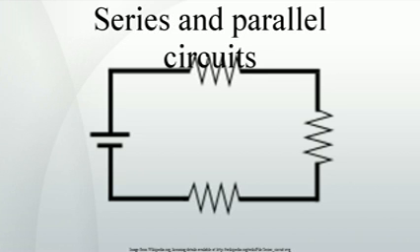This influence is defined by the mutual inductance M. For example, if 2 inductors are in series, there are 2 possible equivalent inductances depending on how the magnetic fields of both inductors influence each other. When there are more than 2 inductors, the mutual inductance between each of them and the way the coils influence each other complicates the calculation.